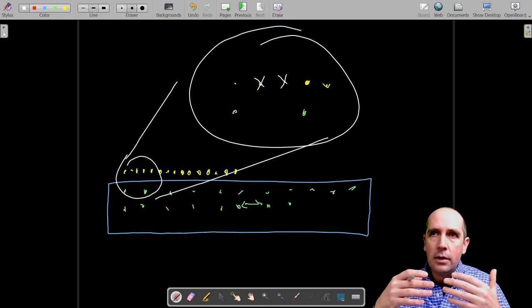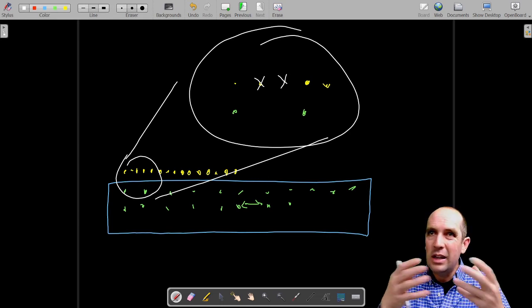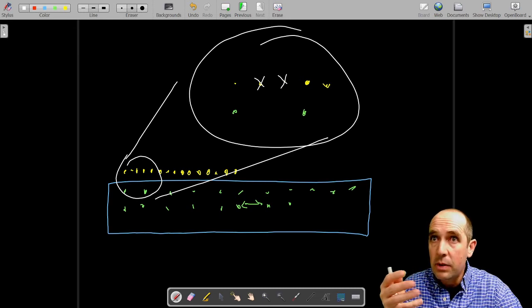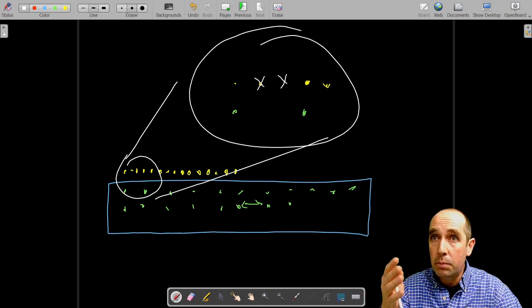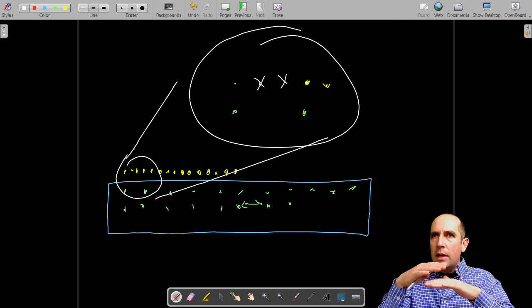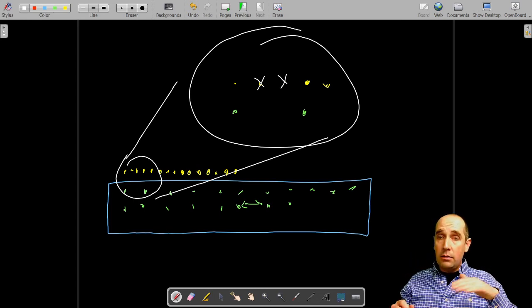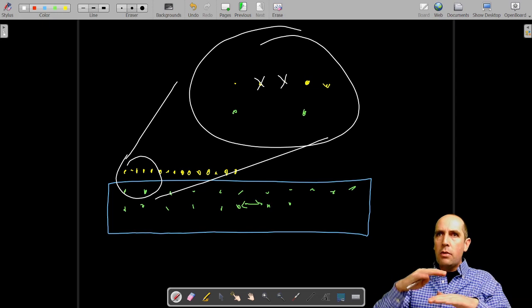So what we will get on top is not really germanium. It could be stressed germanium or germanium rich in defects and atoms not really aligning very well with each other and so on. And that is a problem. And people who do growing, I mean, I'm not a crystal grower myself, but it is something that they are concerned with. And they have found collections of different materials that can be grown on top of each other, just because the lattice mismatch is so small, or is within certain tolerance, and so, for example, gallium arsenide and certain alloys of aluminum gallium arsenide can be grown on top of each other.